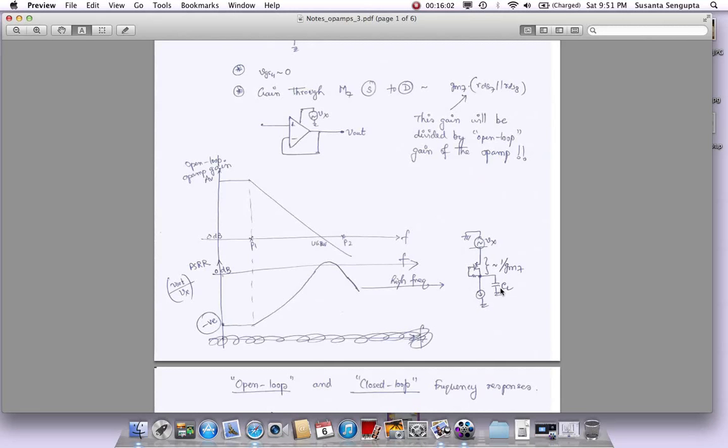Whenever we have a capacitor divider circuit, it will have a fixed ratio. So if the capacitive impedances start dominating, like this is 1 over gm, but if the CGS starts dominating at extremely high frequencies where 1 over omega CGS is much smaller than 1 over gm, then 1 over gm is shunted by this parallel capacitor. So at those high frequencies, it becomes a capacitor divider circuit, and the PSRR or the gain will become flat. It'll flatten out this way. That is something I just thought about now, that I had not put in this plot, but this needs to be extended and it will become kind of flat because at very high frequencies it just becomes like a capacitor divider type circuit.